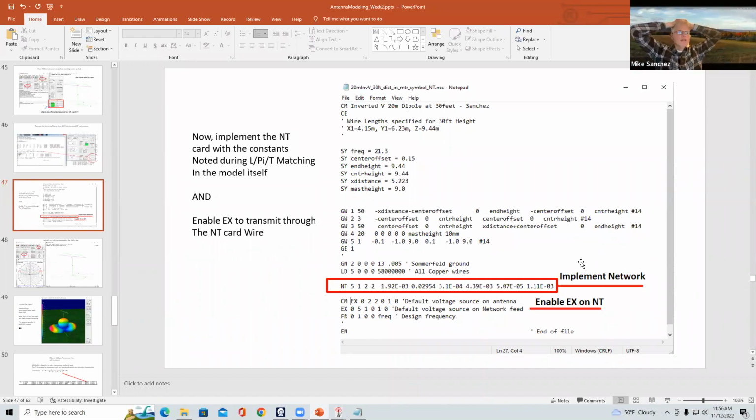So I have in my simulation an OCF, which is 200 ohm native. And I'll show you how to use 4NEC2 in a way that will give you the proper SWR. You don't need to implement it into a card, but I'll show that next time. I'll do that for my off-center fed dipole. Good question. And it's somewhat hidden, not really hidden, it's just not obvious that that's how you would do it initially, given all the complexity in the card format.